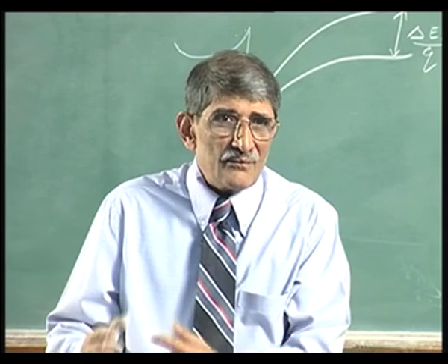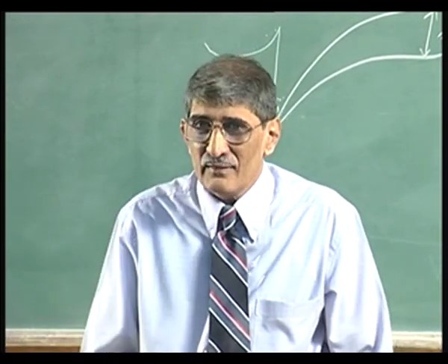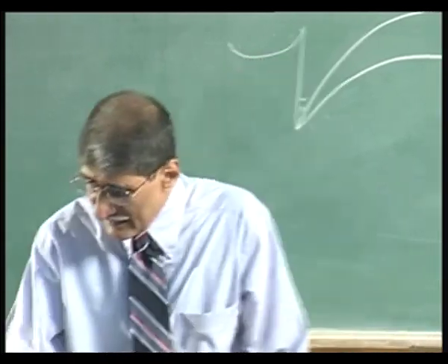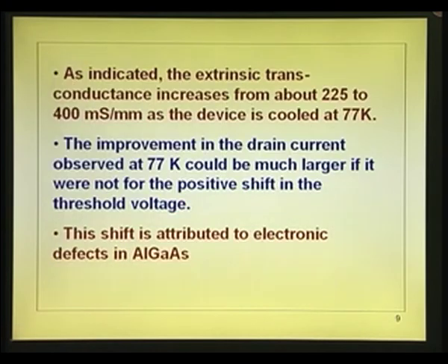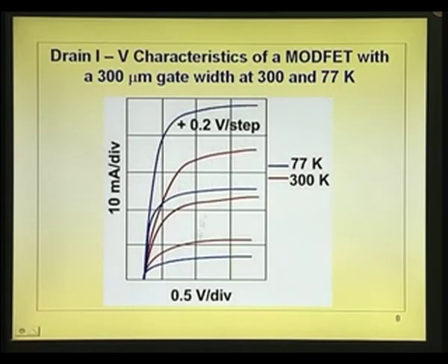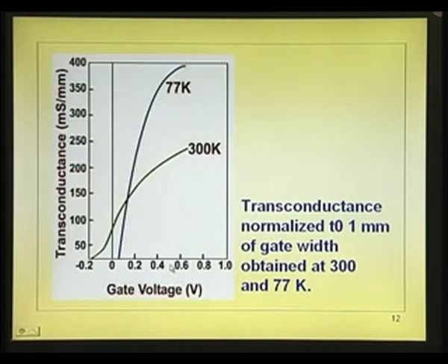What we are trying to point out here is whatever we have said now originally we have got in the form of figure. Transconductance, that is from output characteristics itself, it was evident that the spacing between the characteristics is more, which would mean the delta ID by delta VGS is more. That is why this is sharper. And we do not have to explain further the shift in the threshold voltage, because we have explained that already as due to carrier trapping, okay, and carrier freeze out.